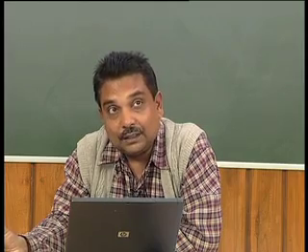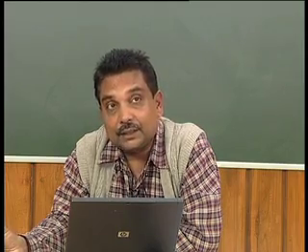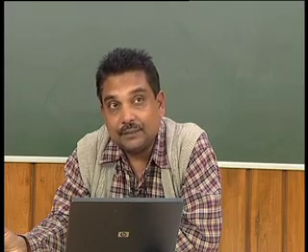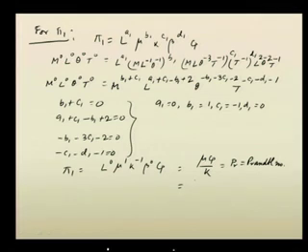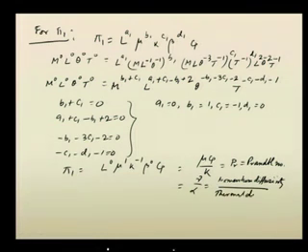This is a molecular level diffusion, whereas in turbulent flow, it is assumed that eddies behave like molecules and that movement takes place. So, as we have already seen, this can be written as nu by alpha, which is momentum diffusivity to thermal diffusivity. So, it is the molecular level transport that is happening for the momentum as well as energy.